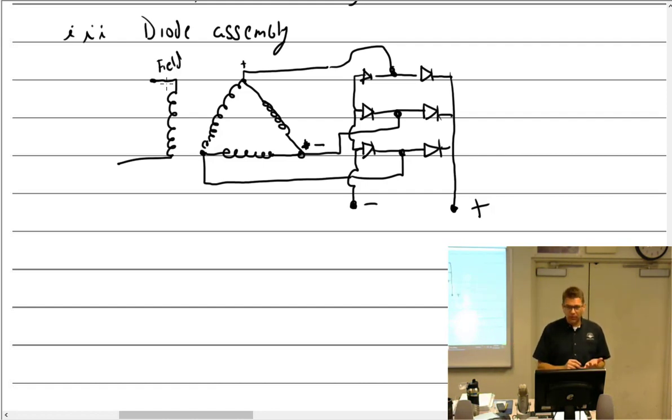Okay, so we saw that we had a 3-part generator control unit, which consisted of a voltage regulator, current regulator, and a reverse current cutout. Well, this needs 2. It still needs to regulate the voltage output, and it still needs to regulate the current output. Now, in older ones, you can still find vibrating coil assemblies. But in newer ones, it's just a solid state little chip. Basically, it handles all of that. But interesting enough, no reverse current cutout is needed.